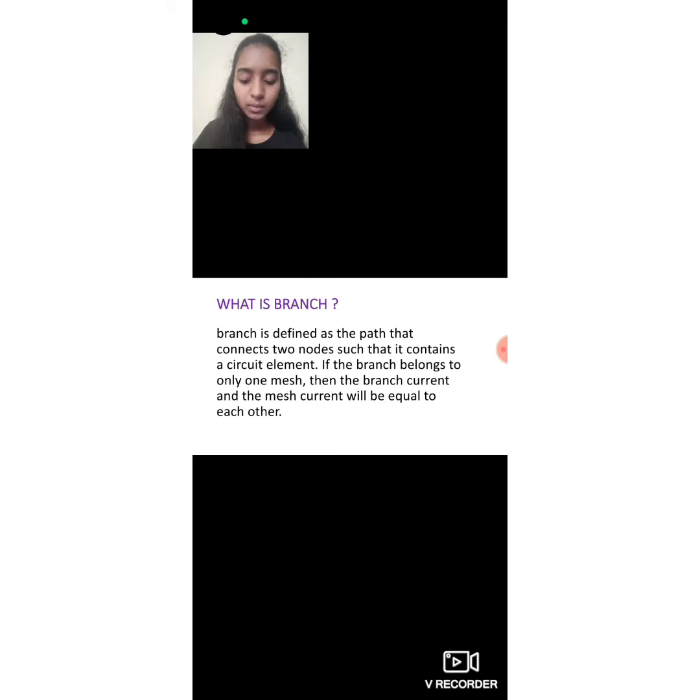The third step is to select one of the identified nodes as a reference node. We have 4 different choices for the assignment. In principle, any of these nodes may be selected as the reference node. However, some nodes are more useful than others. Useful nodes are the ones which make the problem easier to understand and solve. There are a few general guidelines that we need to remember as we make the selection of the reference node.